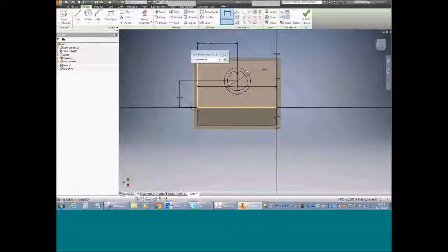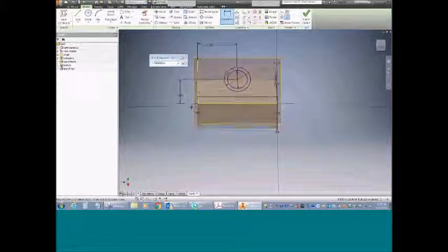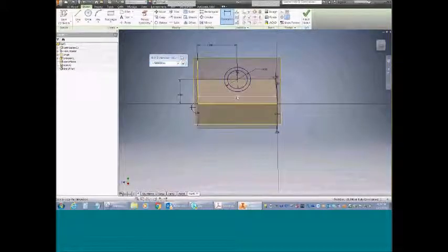I want to show the dimensions for this object. And I want to find that 3 inch. It's right there. So I want that 3 inch dimension. That was my width here. I want to divide that in half. That way, if a design change were to change the width of this part from 3 inches to 2 inches or to 4 inches, I would be guaranteed this feature would always be centered. So it's driven by an equation.